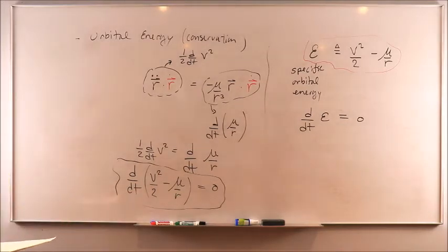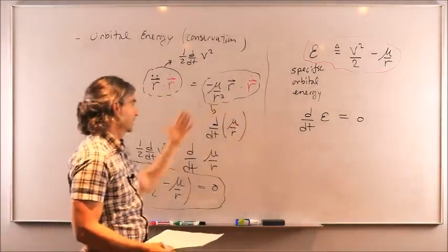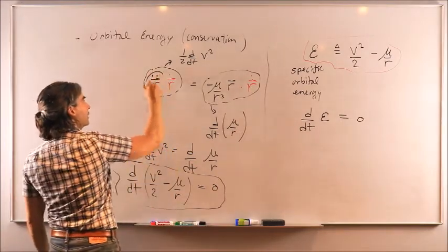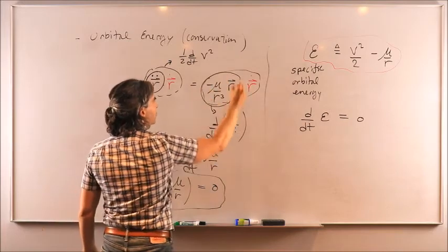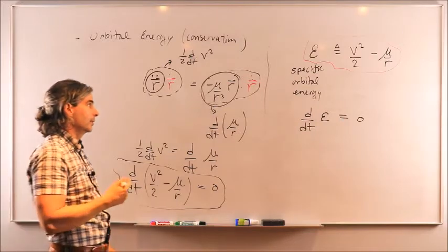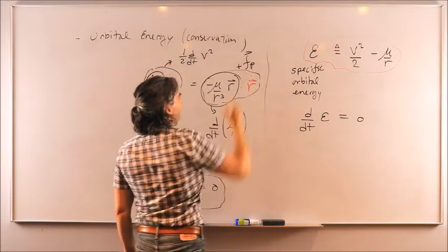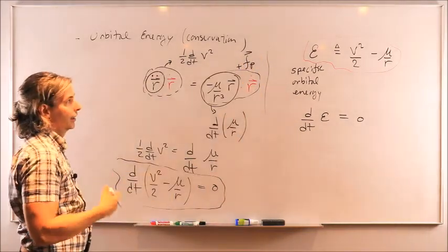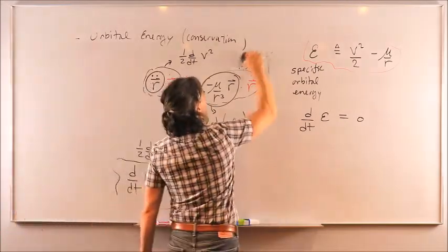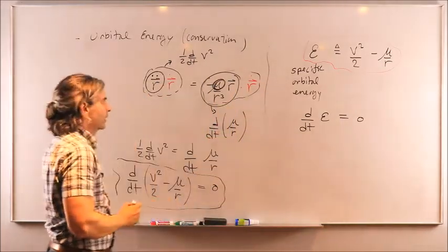And again, this is only valid for the two-body problem because in the process I have used a two-body equation of motion, and in fact that was the starting equation. R double dot equal to minus mu times r vector over r cubed, which is only applicable for the two-body problem because there are no additional terms that would come quantifying the effects of other planets and other perturbations on the motion. All we had was M1 attracting M2 through the mu scalar there.